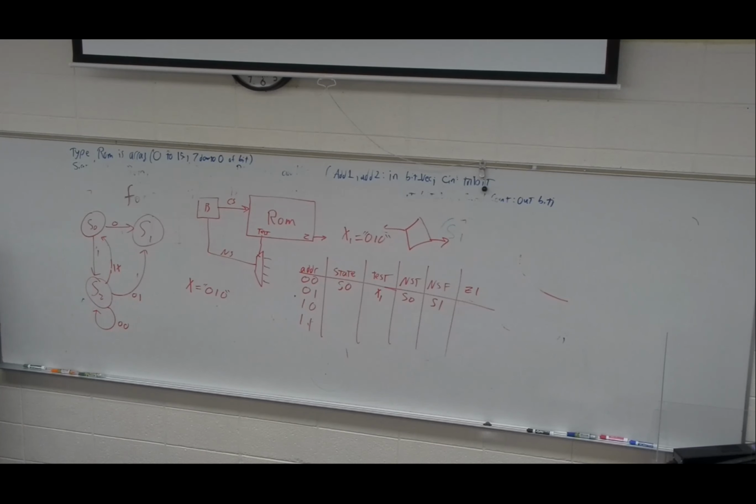Okay, when I tried to think through it, I thought you can't do that and have the same amount of clock cycles. Correct. Your state machine gets slower whenever you add states. And the terminology, I might ask you a question about that, is that I would be increasing the critical path, right?